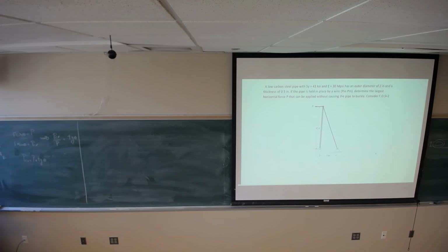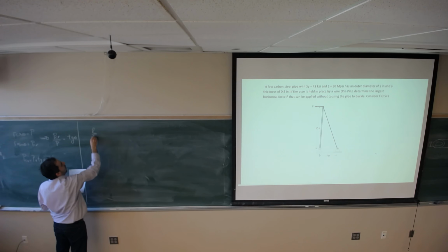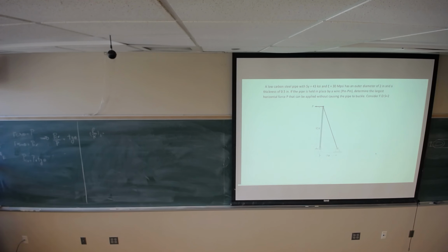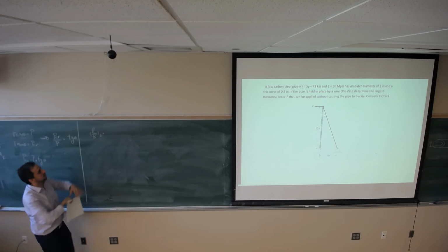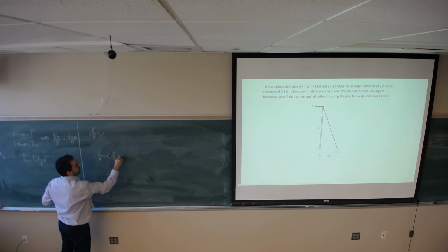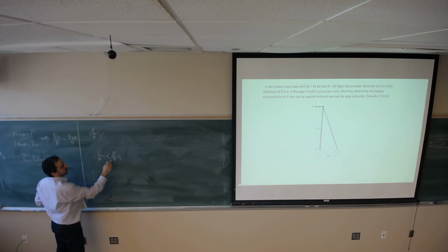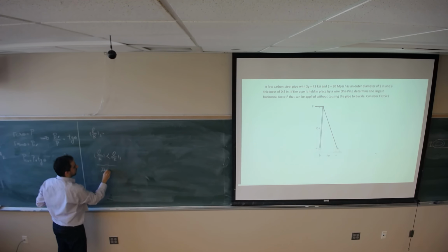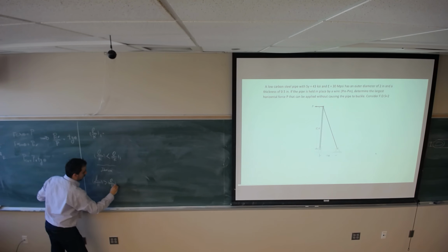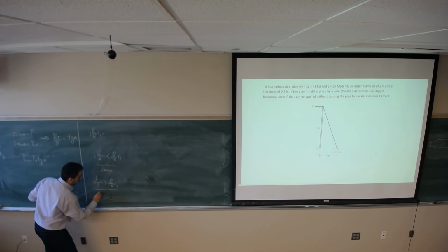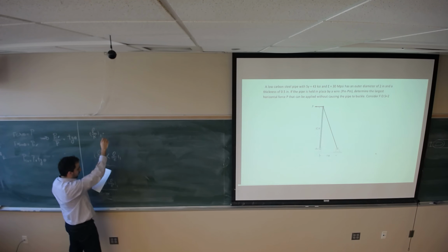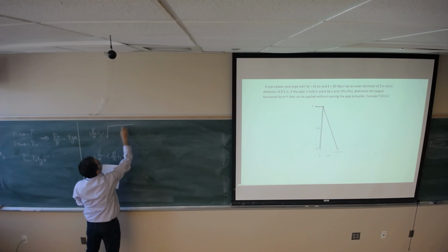First, I will calculate L over K1, the point which is going to tell me whether I should use Euler or Johnson. If L over K is less than L over K1, use Johnson. Otherwise, Euler.